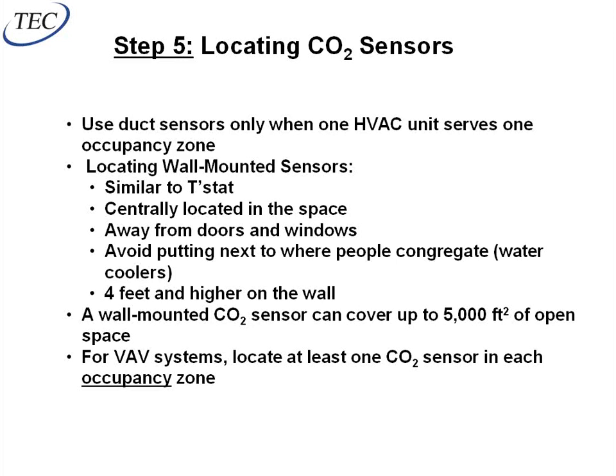for most spaces. And then if I'm having one large area, say like an open floor plan office area, one CO2 sensor can handle 5,000 square feet of open floor plan space. So if I have 10,000 square feet, I'd put 2 sensors in. If I got 7,000 square feet, I'd put 2 sensors in. If I have 4,000 square feet, I could put 1 sensor in. All right, so I could put 1 in that office area, even though it might be served by 2 or 3 VAV boxes. And then for the private offices and the conference room, I would put their own sensors on there.